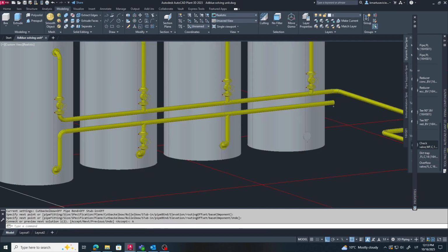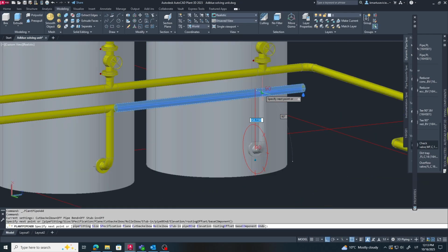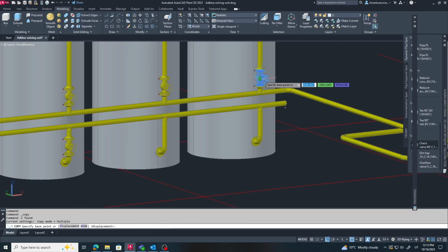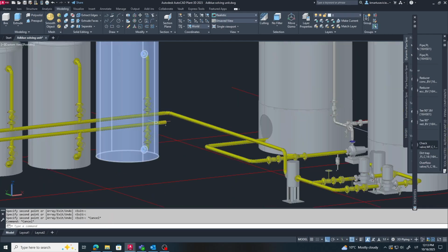Imagine how uncomfortable it would be to open a valve that's 2 meters above the floor. You'd need a ladder every time, which isn't safe or practical. That's why proper valve placement is so important. It saves time, keeps the operation safe, and makes the operator's job much easier.